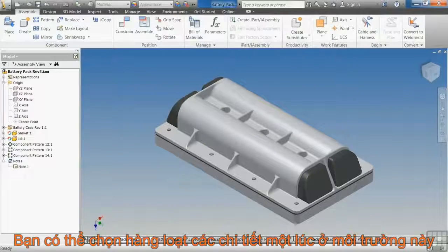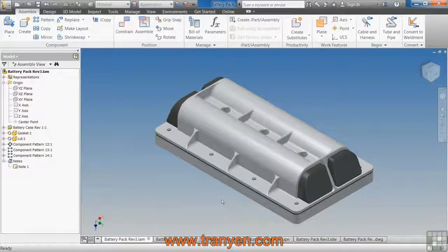You make up multiple parts, come in here to this assembly. You can see as I hover around the different parts in the assembly, it automatically highlights those and tells me, hey, I'm in an assembly environment. You don't really care about the individual features. So when you are editing a feature in Inventor, you're at the part level. So think about it just like you would work on a real manufactured part.